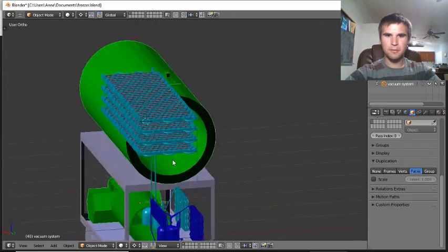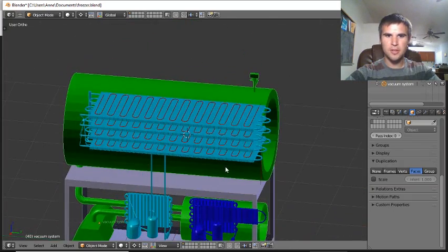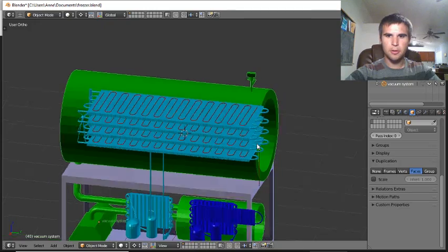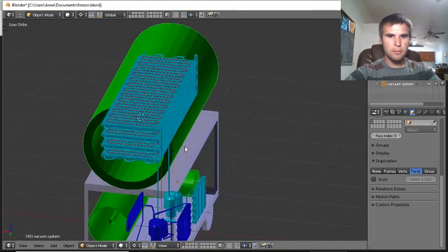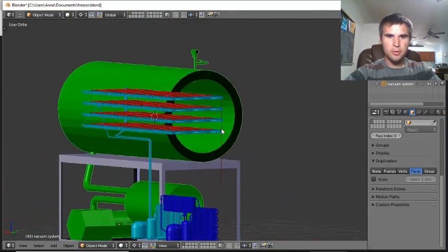Heat strips are cheap and easy enough that I've drawn them in here, see the red portions. If we just lay the heat strip material over the top of the evaporator coils, then they can work together. When one is off, the other one can be turned on.